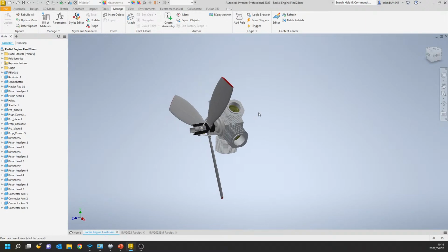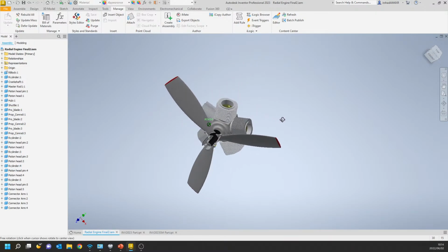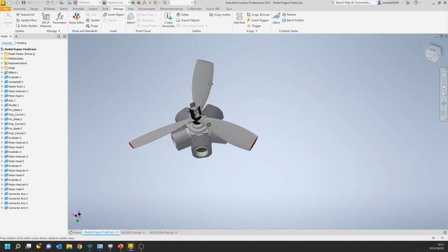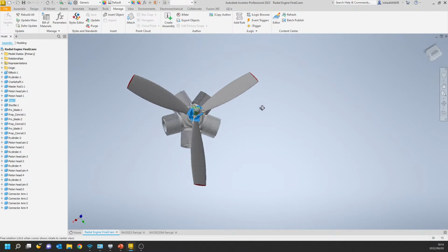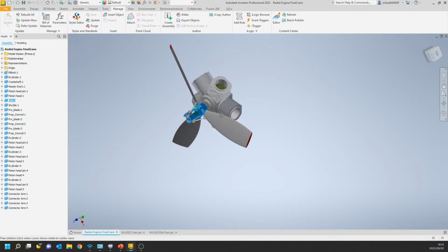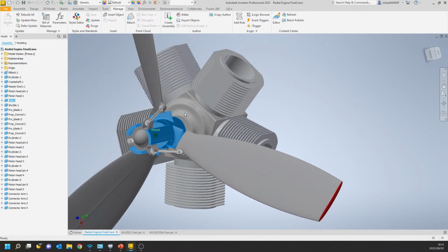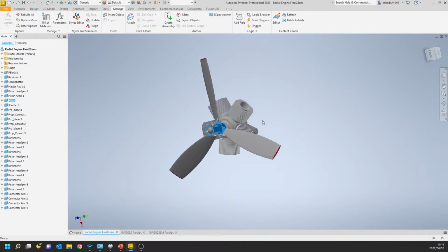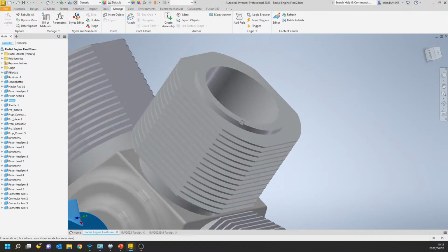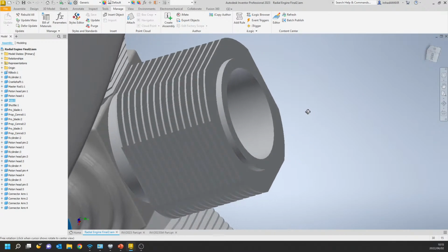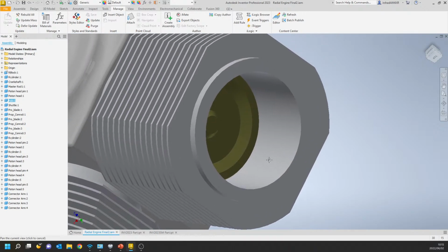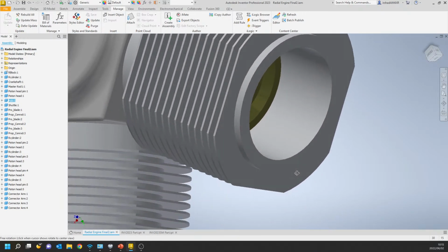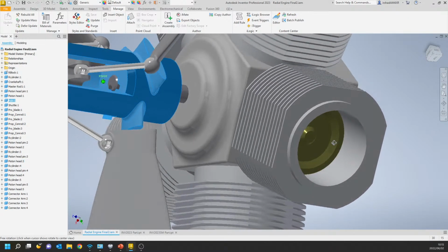Like I said, we have our model, and as stated, we can use our shortcut to orbit, and we see there that our pivot point is the geometric center. Right? So we can find that the geometric centers can sometimes change, but here it is now, my geometric center. You can see the icon there. When the model is partially in view, we can go like this, and we can see that it rotates about a specific edge. So let's go like this, maybe here. So the nearest edge or point will become the pivot.